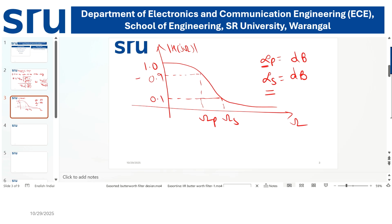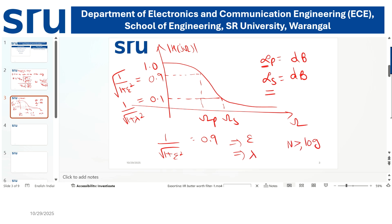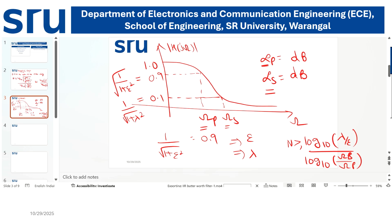Now suppose in the characteristics it is given as 0.9 and 0.1. From this specification we equate this value to square root of 1 by 1 plus epsilon square and that value to square root of 1 by 1 plus lambda square. If you equate 0.9 to the square root of 1 by 1 plus epsilon square, you will get the epsilon value, and next you will get lambda. Therefore you have to use n greater than or equal to log base 10 of lambda by epsilon divided by log of the stop band frequency by the passband frequency. These are the formulas you have to consider from the given specification.